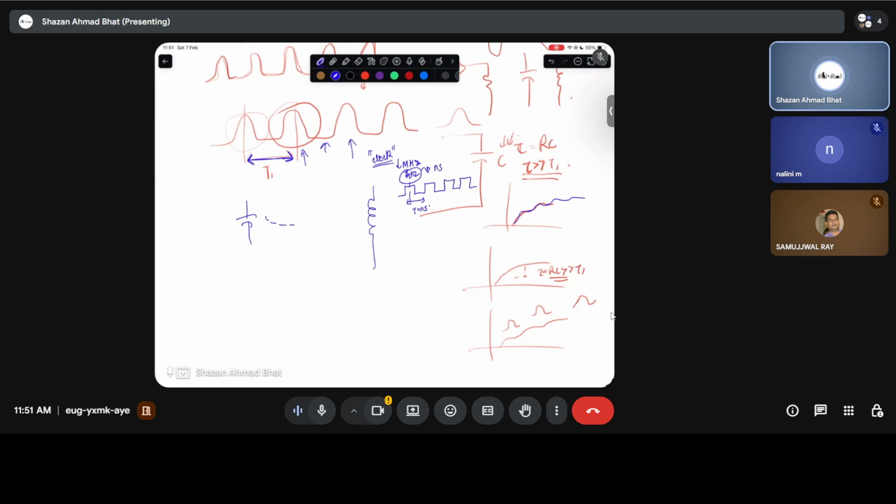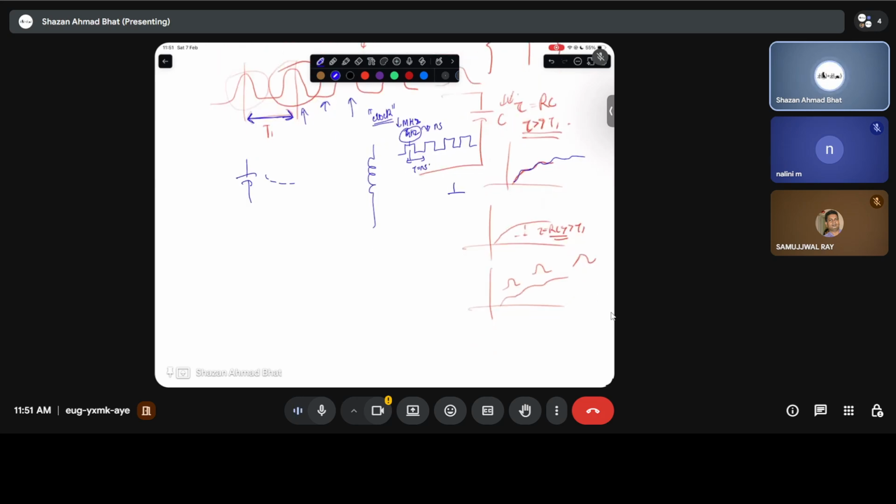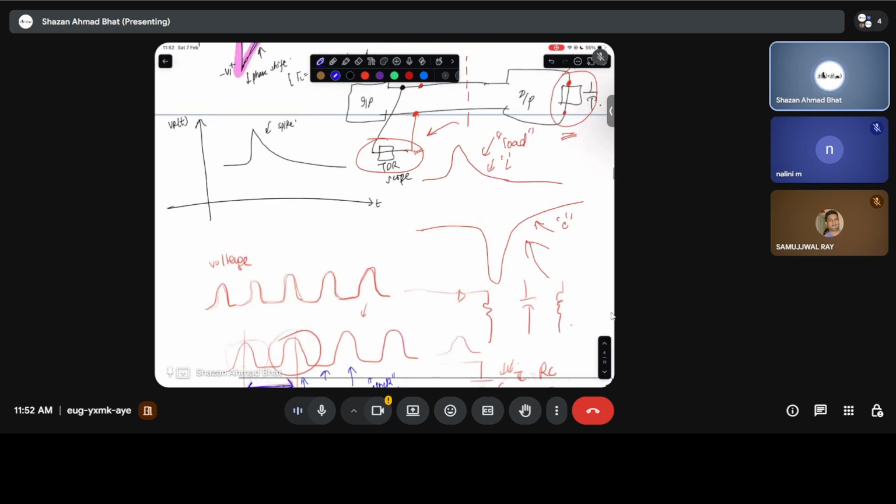And if it has a time period of nanoseconds, that means the load capacitor it is connected to should have a time constant which is less than this T1, so that it charges and then properly acts in the circuit. Otherwise, there will be issues, with charging bumps in the capacitor, which is detrimental and usually not required unless there is a specific usage of the circuit.